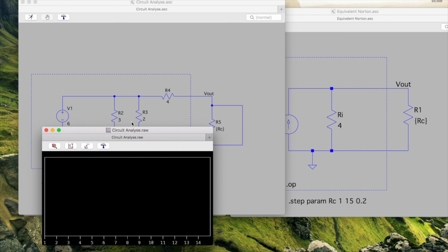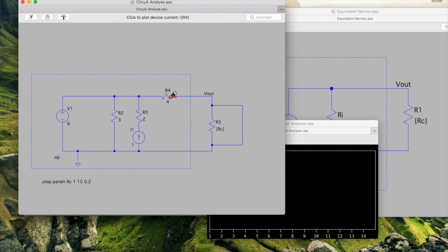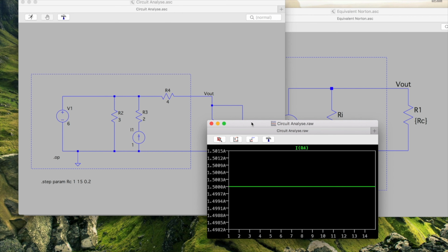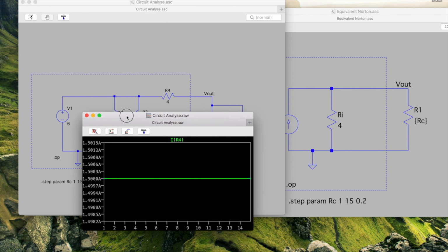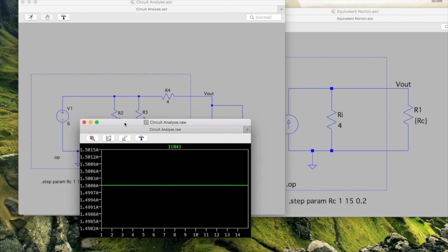I would like to take the opportunity to make a comment about the measurement of the current. When calculating a current, pay attention here to the sign on the element, next to the direction of the arrow indicating the direction of the measured current. Here, we obtain that the Norton current is 1.5 amperes.